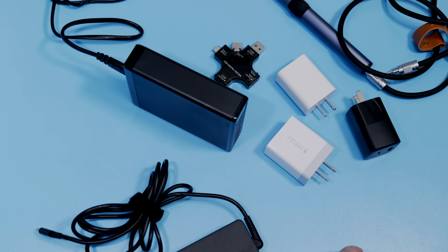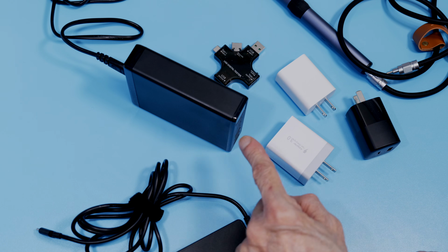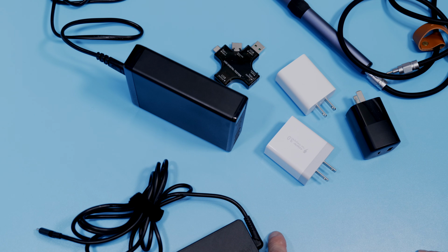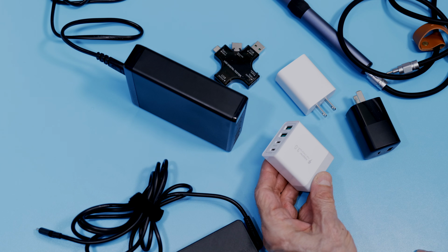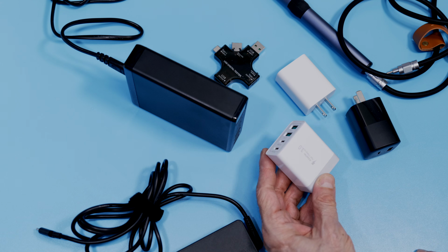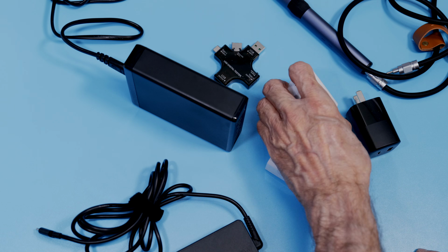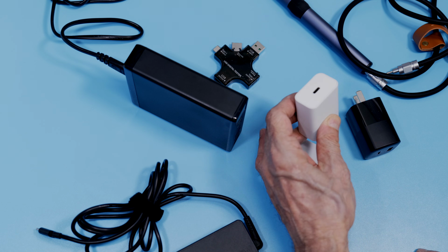Now I've got a few USB-PD power supplies for you to take a look at over here, and as you can see, they're all very different looking, and of course they all have very different specifications. Now one thing you should be aware of when you're choosing a USB-PD power supply is that not all of them support all the USB-PD voltages. For example, this one here only supports the 5 volts, 9 volts, and 15 volts, so it doesn't support 20. And this one only supports 5 volts and 9 volts.